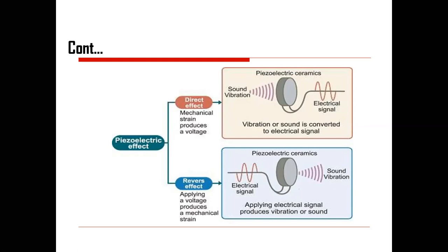Now, how are you going to correlate this effect? Suppose this is the position of the sound generation and this is our crystal. If I vary the position, this is the displacement of the sound-generating signal. If I reduce the distance, the sound will strike the piezoelectric ceramic maximally with high intensity, and the generated output will vary. If the distance is far away, the minimum sound vibration will reach the ceramic, and the electrical output generated will be the minimum.